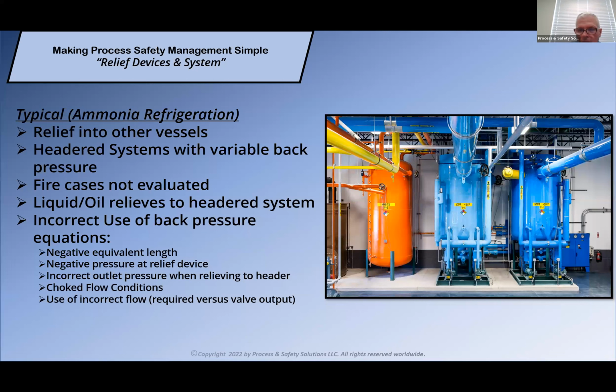They should be going in other places such that you're not affecting the performance of those relief valves that are in there, even if you have drains in there. So typically drains get opened very frequently, and you could have a number of feet of liquid sitting on top of that relief valve, rendering it inoperable as a result.